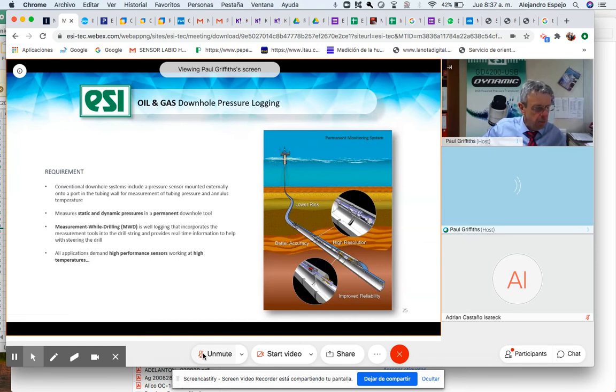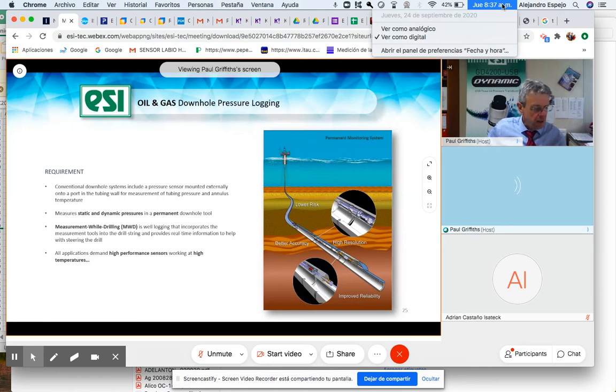So temperature and pressure are really important, and they can calculate the volume of oil in the well by drilling one or two holes and comparing the pressure readings at different points. They can calculate quite accurately the volume of the oil. They can also monitor the pressure. If pressure in the oil well deteriorates over a period of time, that suggests there may be a leak, or you're losing your oil reserves. So it's really important to measure pressure in these downhole applications.